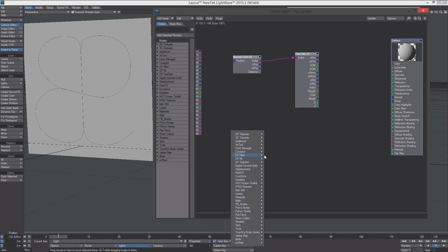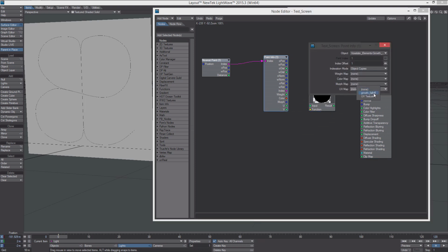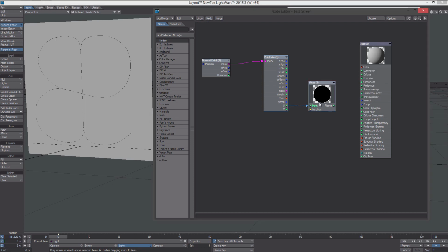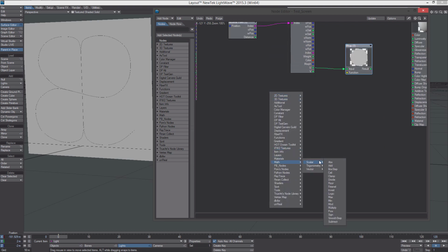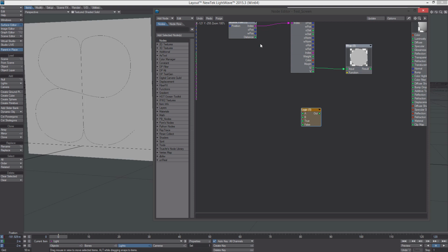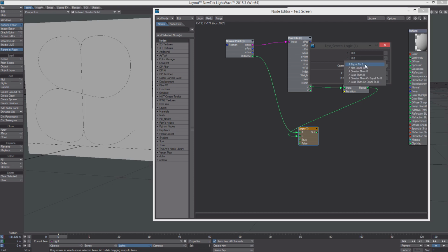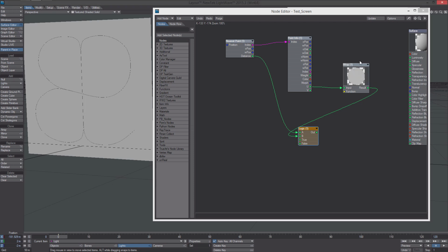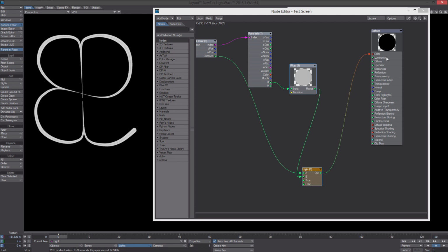And to start out with, we'll get a functions wrap, and I'm just going to take the U. I'm going to select our UV map. It's called growth fall off, and I'm going to take the U into the input of our wrap. And so if I get a scalar logic, and if I get the distance here, and I get our UV map, and if I just say if A is less than B, you'll see what that gives us. So you can see what it gives us.